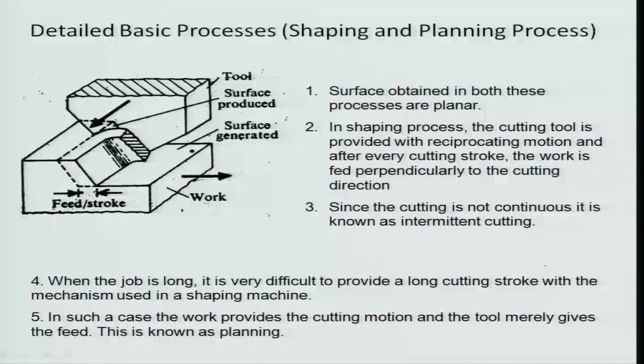So, if we talk about the basic processes of machining, it is really about peeling off of the material. As I told you earlier, there is a metal tip which would be engaged with another metal, which is the workpiece. In our case, the metal tip is harder in comparison to the workpiece, and it actually plows into the metal and starts to peel off the metal. That is how you do conventional machining, or that is how the chip formation takes place within the system.